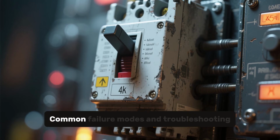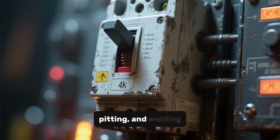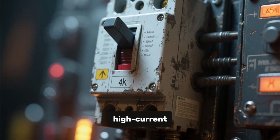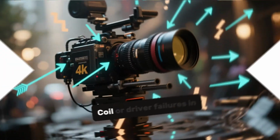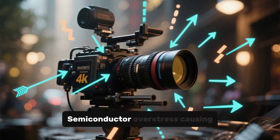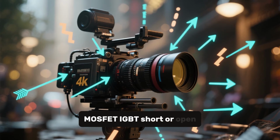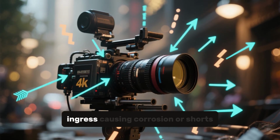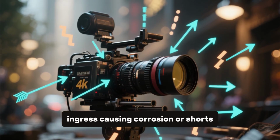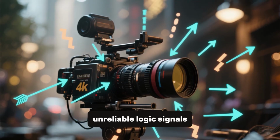Section 11. Common failure modes and troubleshooting. Contact wear, pitting, and welding from arcing, typical in high current mechanical switches. Coil or driver failures in relays and contactors. Semiconductor overstress causing MOSFET or IGBT short or open. Environmental ingress causing corrosion or shorts. Bounce and intermittent contact causing unreliable logic signals.